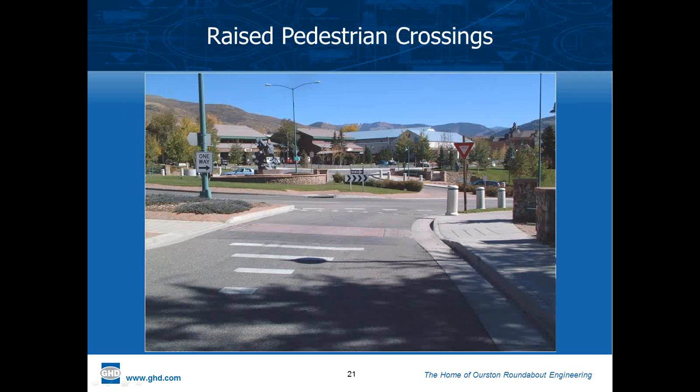The raised pedestrian crossing has been researched along with devices like the hybrid activated walk signal and the rapid rectangular flashing beacon, and surprisingly the rates of yielding and compliance and the responsiveness of drivers was quite high with raised crosswalks. In fact, the point at which drivers yield on average was, I think, in the 6 to 8 second range compared to other devices. It was quite good, even signals or rapid rectangular flashing beacon. Crosswalk ranked very high, rather surprising. Designs like this, you can see there's not a great visual here, even with the contrasting pavement and some of the markings here.